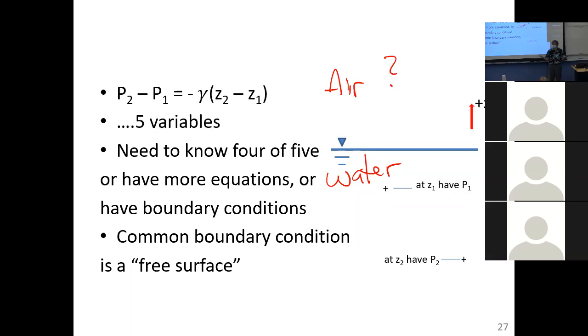What do we set all of our local gauges to? 0. 0 psi, 0 Newton per meter squared, 0 Pascal. That's the local datum. Just like as far as a local datum, we can say that Z is equal to 0 right at the fluid surface interface. That's a local datum. So what you know is when you have atmospheric pressure operating on top of a fluid surface, that's known as a free surface.